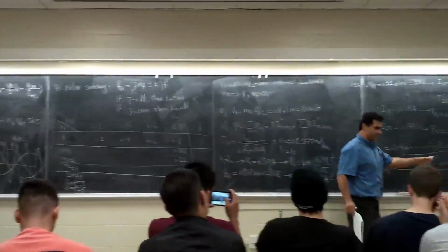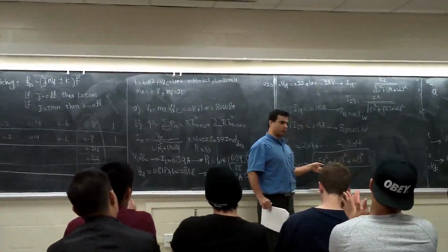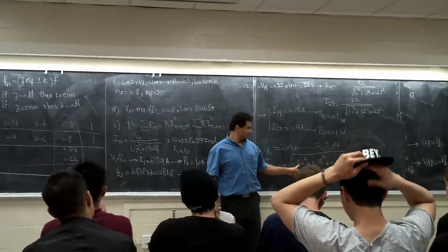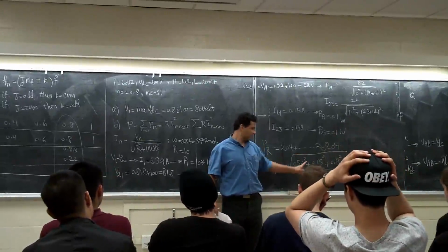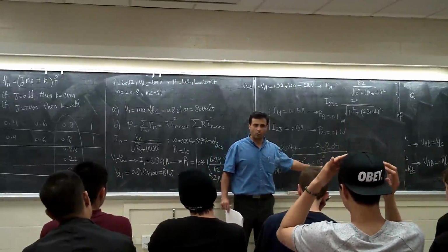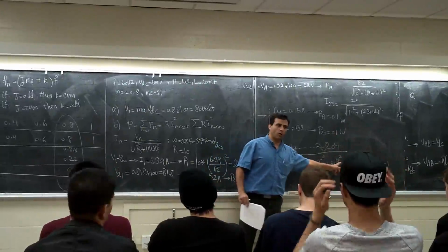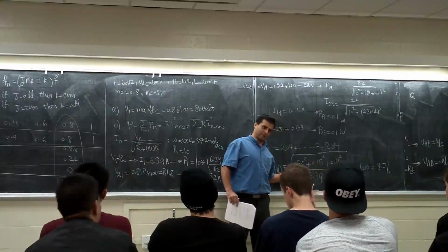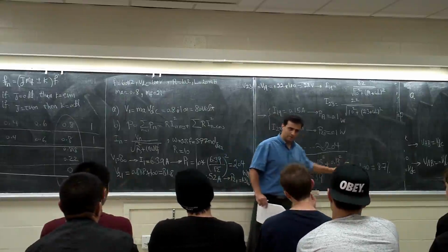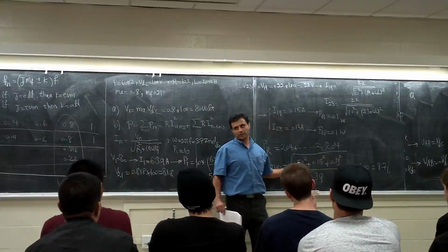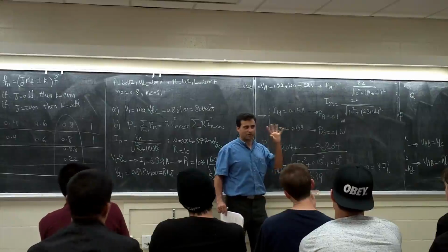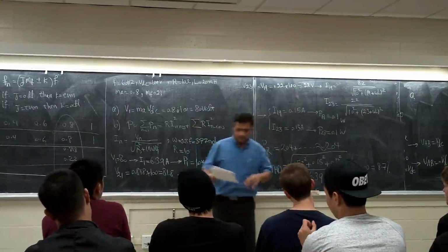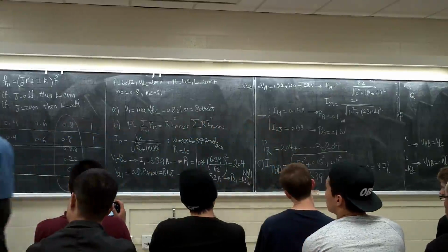If you go with the THD, this one is going to be 0.25, right? To the power of 2 is going to be 0.20, because I'm going to use this assumption now. 0.5 to the power of 2 is 0.25. How much is this one? 0.01 or 0.02, something, right? So these two are much, much smaller than this, right? Even I can get rid of these. Because the THD is basically based on this one, right? I'm going to use this concept for the next problem, only this one for the THD. Now, the next problem is saying this.